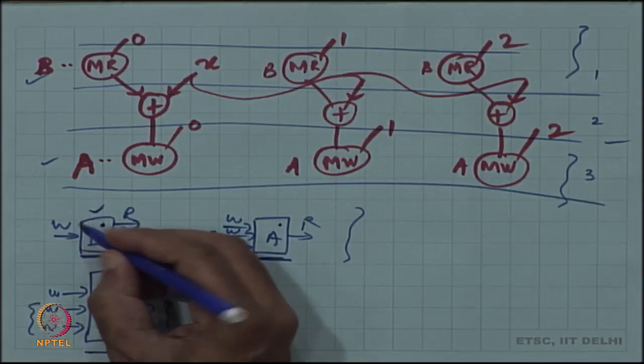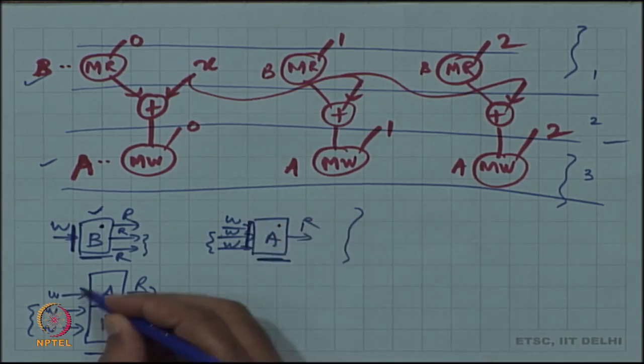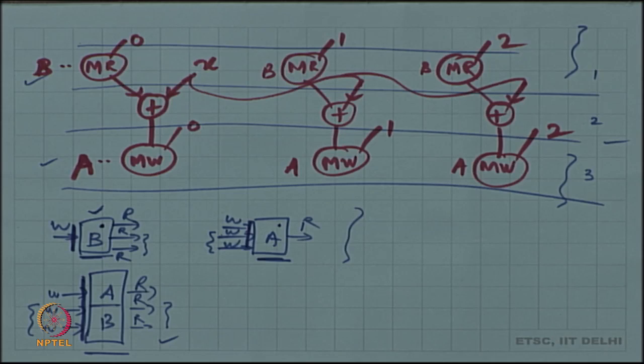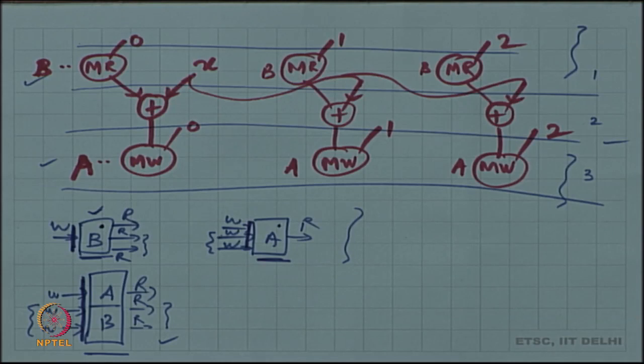It may not be as simple as 0 and 1, but it is known. Also, remember what we talked about the decoder here. There are some arguments with respect to the larger decoder being the sum of the smaller decoders plus a little decoder, if you know how a decoder is designed in terms of pure logic. But that is one argument, but the other is also that when the storage is split like this, there is routing related overhead that is usually big. When it is a compact decoder like this, the area overhead could be less. In general, when you split a larger memory into multiple smaller memories, you expect an area overhead.